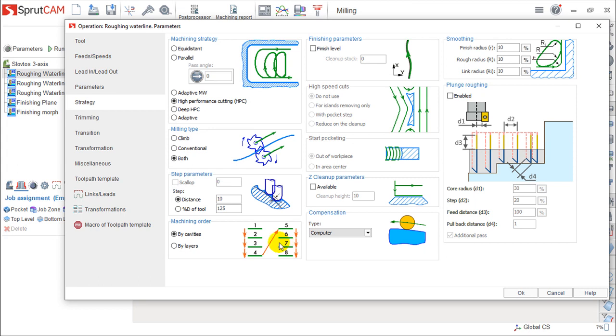This graphic is quite interesting, because maybe this model is not the best suited for this parameter in particular, but every time we have something with a lot of pockets, this type of tool by levels, every time it cleans a level, and if it finds a closed area where it needs to go up to go to another place, we can choose this by layers, where it will clean a layer completely and go up the times that it needs, or doing by cavity.